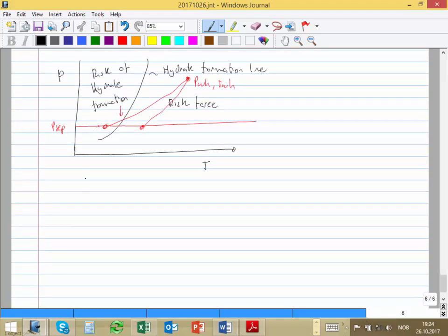The way to deal with that is usually to use a hydrate inhibitor. Remember what we discussed about the water molecule, HOH. If you have only water, the molecules just accommodate themselves and are happy and nice. But then you come with something else that is also very polar and is going to interfere with the formation of this cage.